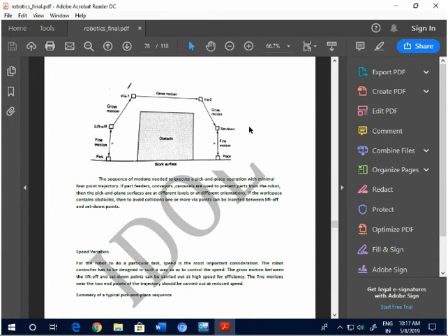So based on the sequence of joints used by the major axis, you are classifying the workspace into 3 categories. Okay, that is, what are the workspace types? You have 3 types of workspace envelope. So first is your total workspace envelope, or the gross workspace envelope.